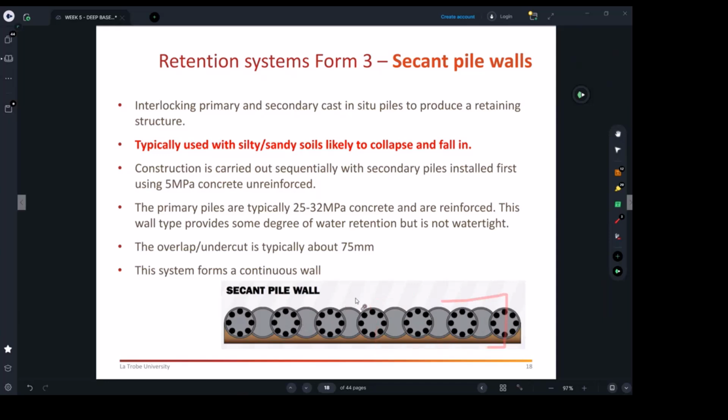Okay, so obviously with these ones, they will stop here, and they will make such arrangements just to allow things to happen. And then they can start the next stage, whether same day or next day, up to the timing and how things work. So yeah, it is slower. It's got some waste there, because you're placing concrete, then you're excavating it again. But sometimes you just need to have this process. The secant piles, you just need to have the piles sticking to each other, right?